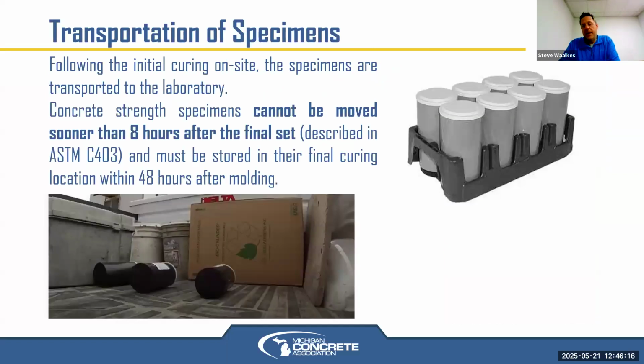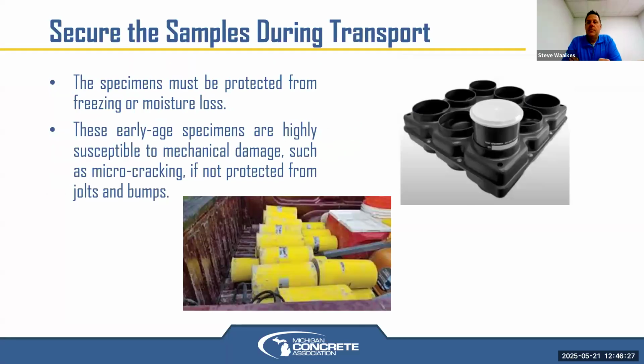Transportation, as I mentioned, they have to be in the field for 8 hours until final set, and before 48 hours they need to go back to the lab, within 4 hours. So there are different devices that can be used, racks. You don't want them rolling around the bed of a pickup, banging around, especially depending on your driving habits, because that can pre-crack them and damage them, so that when they're actually loaded and tested at age 28 days, they might have some damage from that.